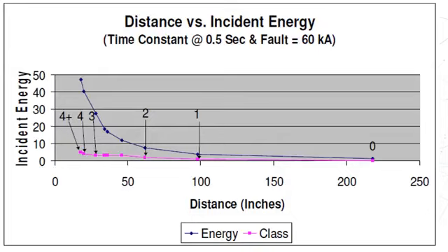So this was a complete work scope. The PPE was selected based on the minimum distance he will be required to work at during this scope. It was already identified that this person will be performing live work at a minimum working distance of 36 inches, at a minimum distance of 18 inches. The PPE he was wearing was rated for that particular voltage level, so he's allowed to perform the task.